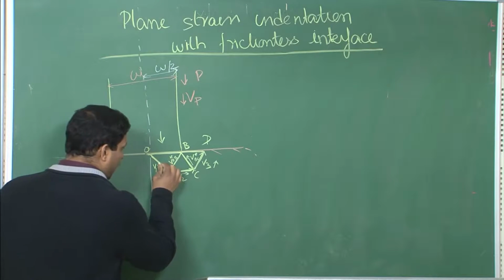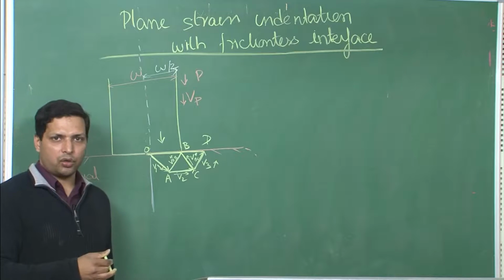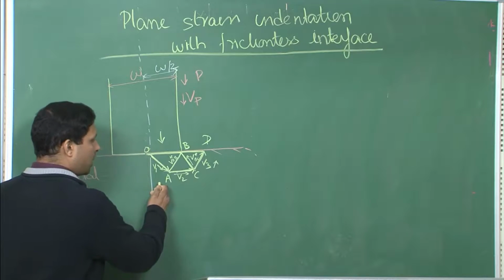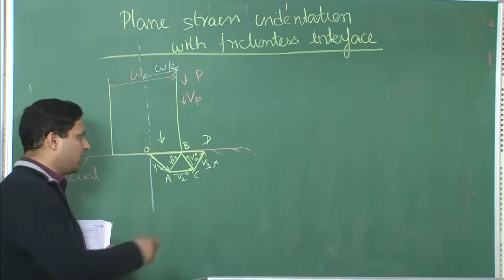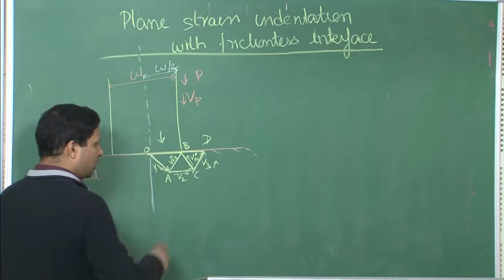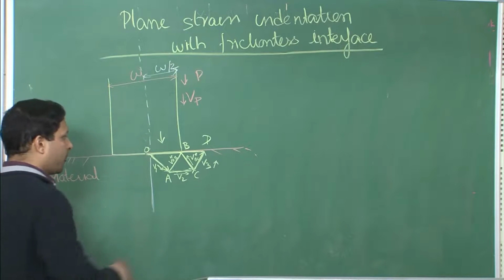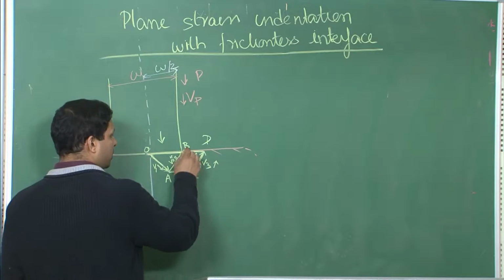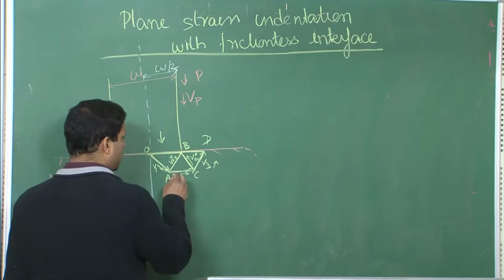What is happening at this interface? Outside this, if you remember, if you go back and look at the lecture notes, the material is supposed to be rigid. So, there is rigid material here and the material is moving here. So, there is shearing also taking place at this place, along this plane, and along this plane. So, we have shearing here, here, here, and we obviously had shearing because these are the internal shearing taking place when we have velocity discontinuity.